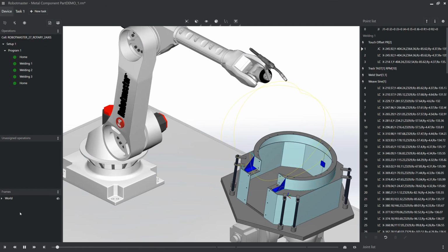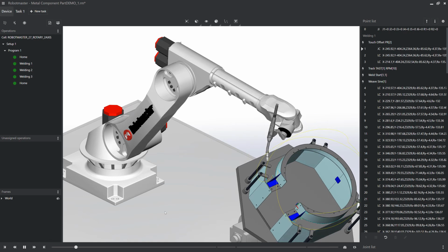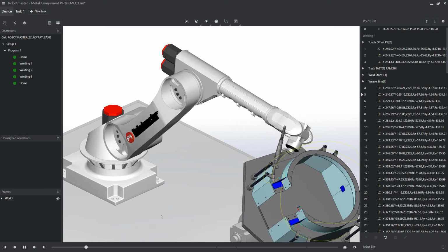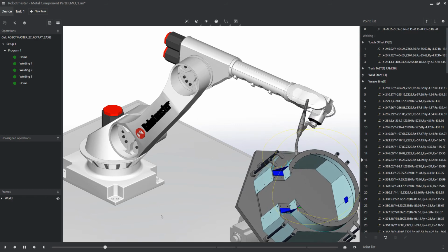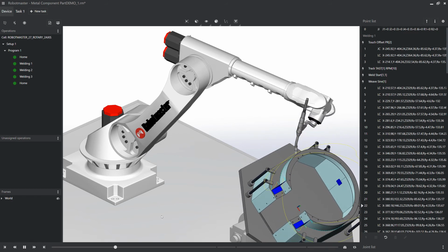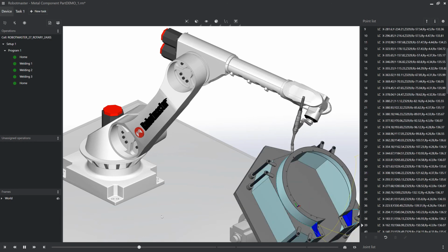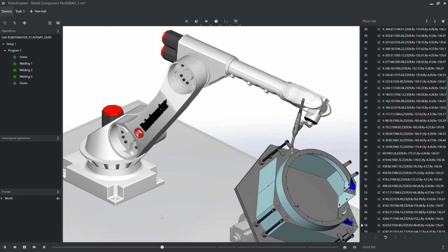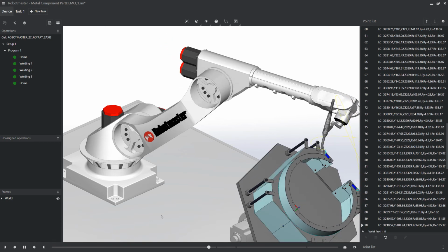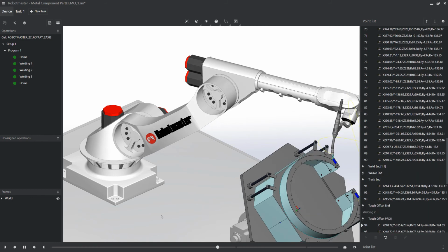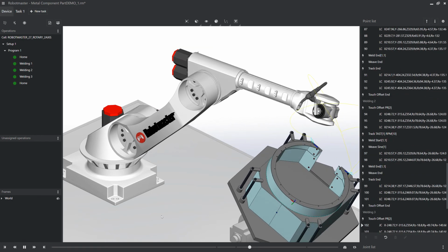Robotmaster version 7 has the most technically advanced rail or rotary table management methods in the robot programming market. One function loved by Robotmaster welders is the ability to do a combined autosync with a 2-axis rotary table. In this mode, Robotmaster automatically manages the axes of the rotary table, so the welding nozzle is always held at a desired angle with the least possible movement, thereby giving the best quality weld possible.